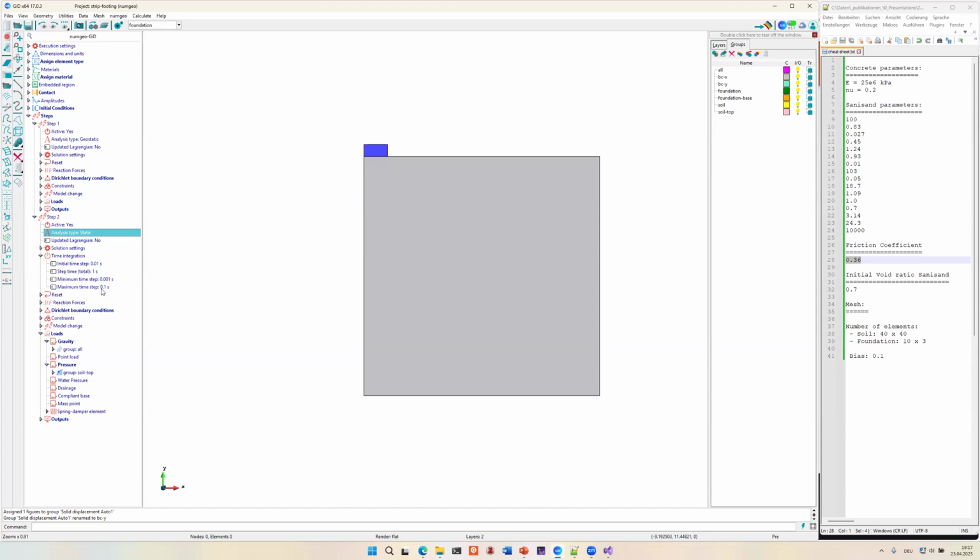So we specify a maximum time step. In this case, it is 0.1 seconds. And if the convergence rate is very bad, the solver will try to reduce the time step to capture maybe better the nonlinearities, but also for that, we can define a minimum time step. And once the total time of a step reaches 1 second, the step is terminated and the simulation is finished. So here we will now choose just a lower initial time step of 0.005 seconds.